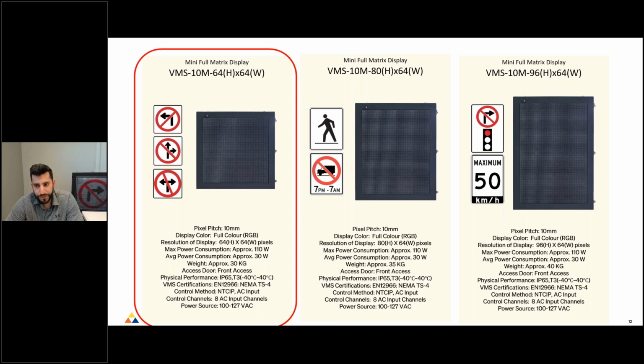And we really decided to standardize on 3 primary sizes to support blankout sign applications. The first size that I have here highlighted in red is our 64 centimeter by 64 centimeter board, and that's the one board you're seeing behind me cycle through the various turning restrictions. This model is excellent for posting anything related to your standard turning movement restrictions, RB12, RB11. It's 64 by 64 centimeters.